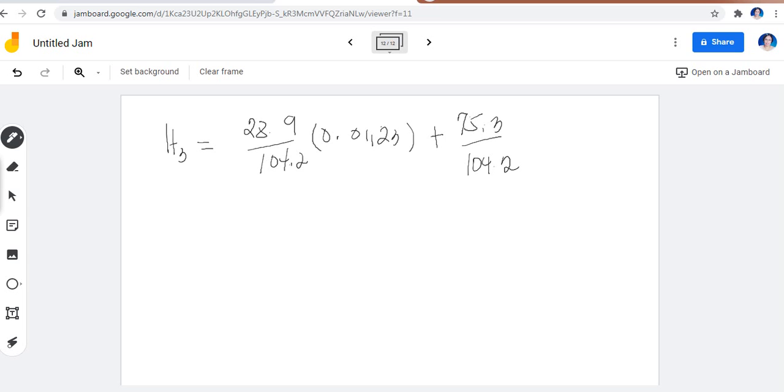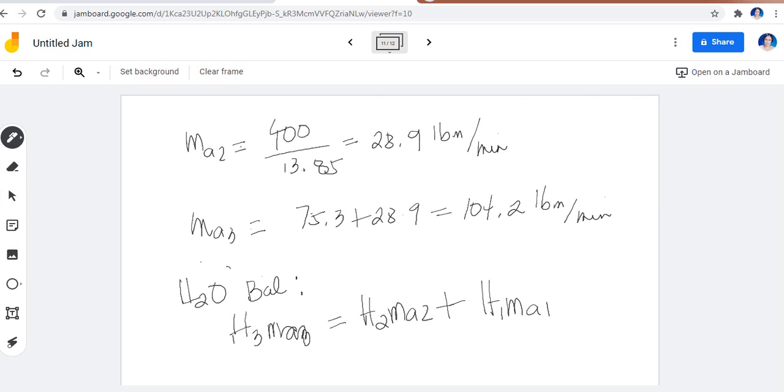So you will multiply this with its, for stream 1, 0.00867. So this is actually Ma2H2, Ma1H1. We just divided it by the Ma3 to get H3 coming from the formula that we have here, so that we will know the humidity H3 of our resulting mixture.